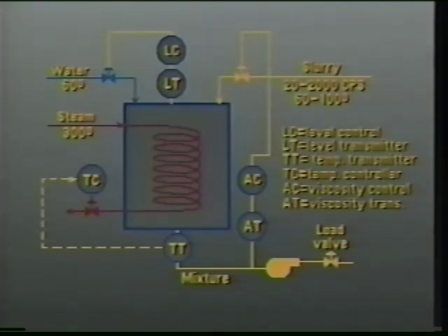Your first move should probably be to add the instruments needed to create feedback loops. After these are in place, you can begin to address special, more advanced control schemes that may be necessary in cases where there are significant time delays, dead time, or load disturbances that make simple feedback ineffective.